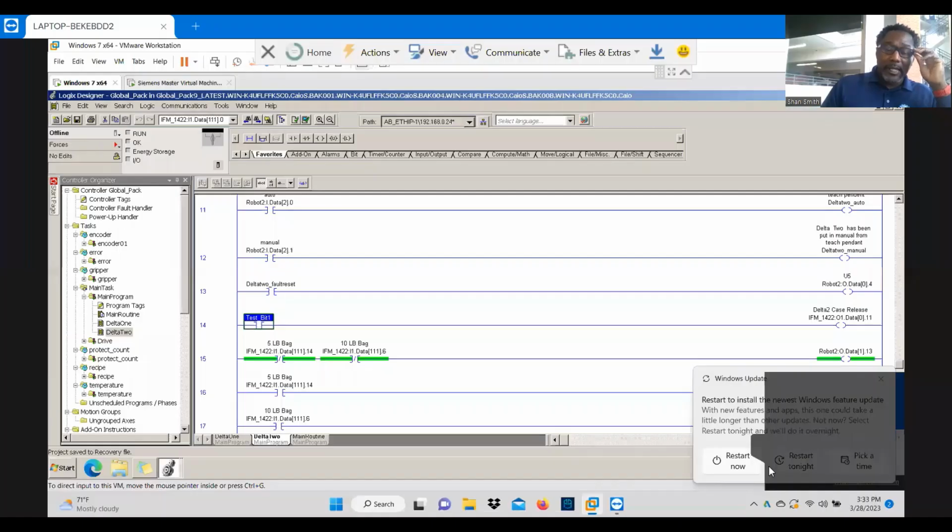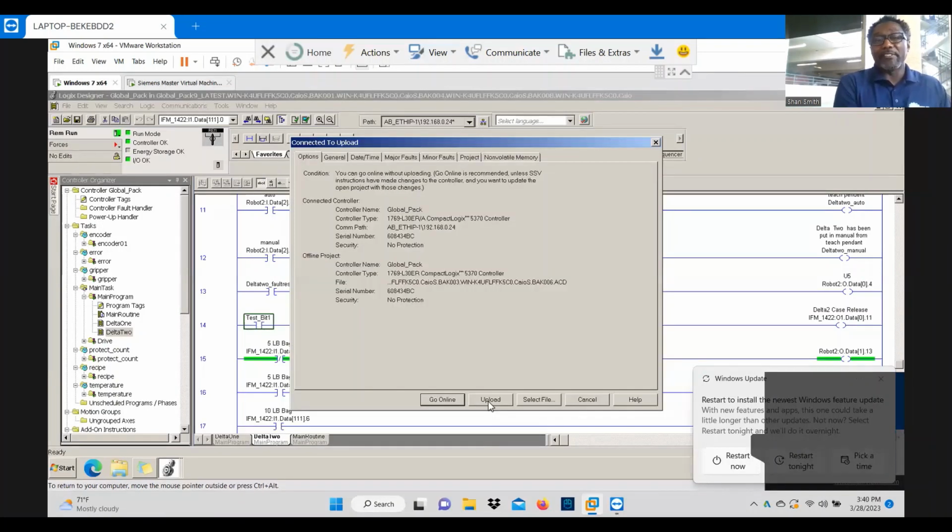All right, so currently I am using Teamviewer. Make sure that backup's in a safe place, a great storage place. Another thing I'll add is that if for some reason your Ethernet cable gets broken during a download, you're gonna basically brick the PLC. So what you don't want to do is not have a backup before you start making changes. Make the backup, put it in a safe place, then make changes. Let's make this upload.